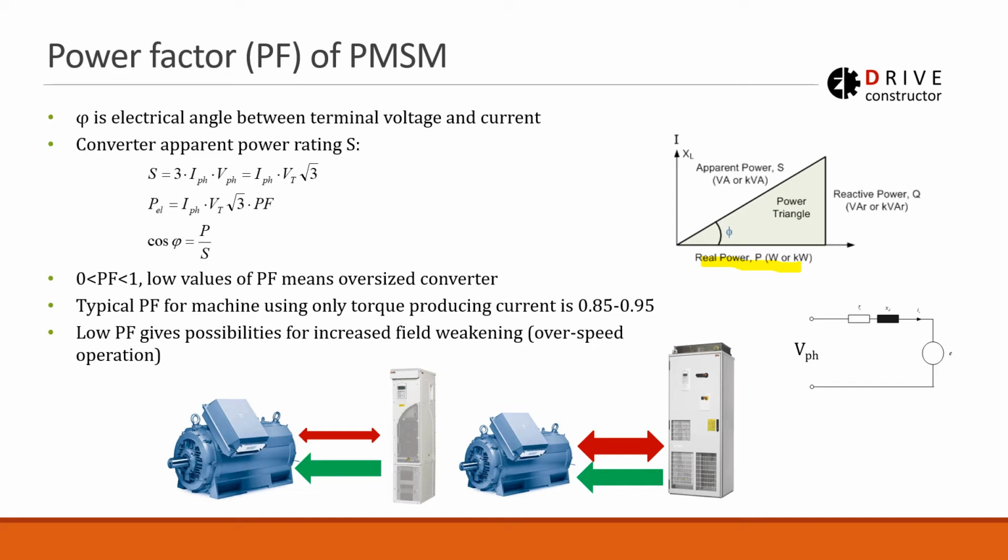It is a sort of useful power. But there is also reactive power, which is basically just a pulsing power between the grid and the electric machine, or the frequency converter and the electric machine. So it is more or less parasitic power, which we usually do not need. And apparent power is in a way a product of these two, the real and the reactive ones.